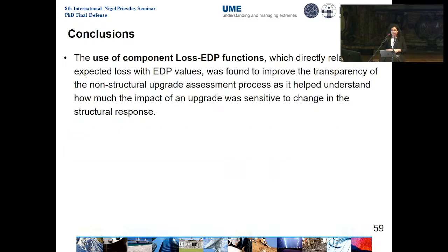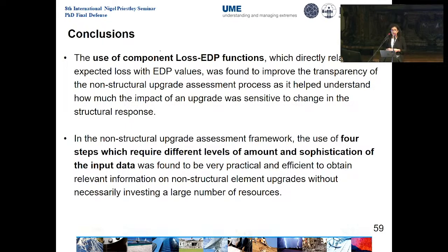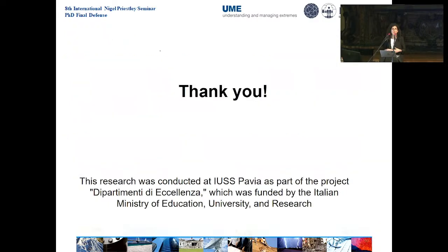We found that the use of component loss EDP functions, which directly relate engineering demand parameters with expected losses, improved the transparency of the non-structural upgrade assessment process, as it helped understand how much can be the impact of a non-structural upgrade and how sensitive it can be to change in the structural response. And finally, we found that the use of 4-step, which requires different levels of sophistication of the input data, is very practical and efficient to obtain relevant information on non-structural elements upgrades impact without necessarily investing a large number of resources.